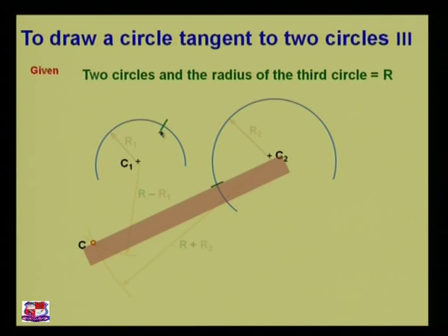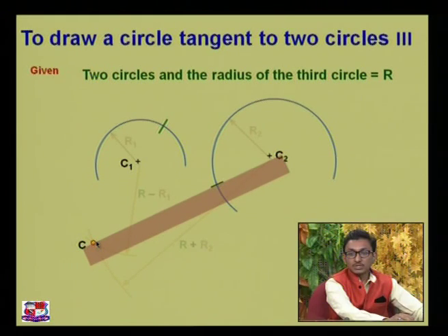Now as you can see, our tangential curve will be generated over here. We have marked these two points. We have got our center point. Now we will use the compass and draw a tangential circle to these two circles like this. As you can see, we have drawn this arc.